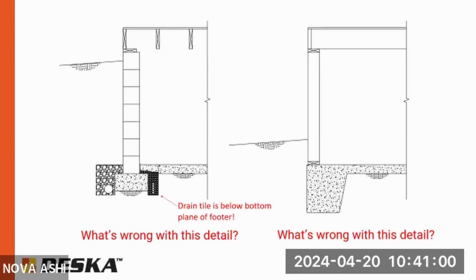This one here, in this case, is a monolithic footing. The slab and the footing are one. You can see it's built down, and the grade is up against the facade of the building. We see this a lot with townhomes, whether the association does it or a neighbor does it. They don't know any better, and then it ends up becoming a problem. So the grade's above the foundation, and we're assuming that's not a timber foundation above there. The solutions are you lower the grade back to where it used to be, up against the masonry foundation or concrete footing here, or you can build a stem wall.